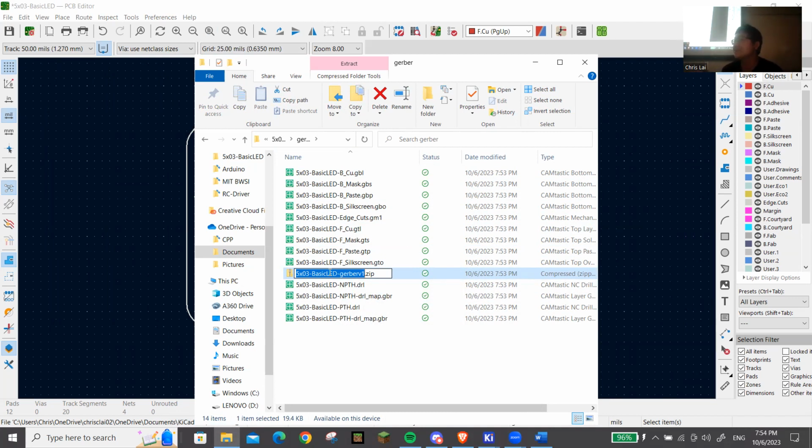All right. So again, you don't have to go through this step if you don't want to, but I will have these instructions up for you at the end of the workshop or maybe a few days after the workshop so you can follow it at home. So if you want to do your own projects and make a more complicated PCB, maybe one of those Blinky learners over there or your own robotic controller, then you can go ahead and do these same steps. There will be a lot more components. There may be more obscure footprints you have to get, but all of the core steps are the same. Just step through it, then run the DRC, make sure it's valid, order your PCB, and then reap your rewards from your projects.